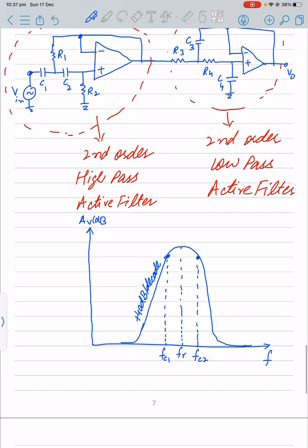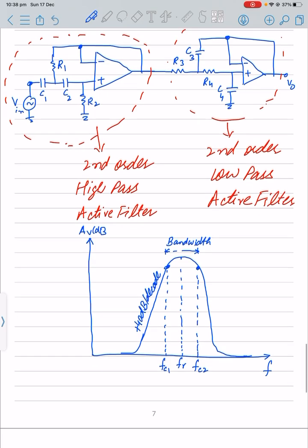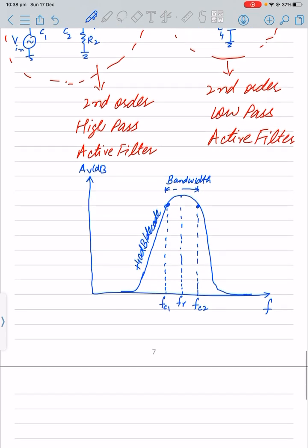So that will be the frequency response of this band pass filter. It allows only a bandwidth of some particular frequencies to pass through it, and it blocks the rest of the frequencies. One of the ways we have achieved it is by cascading a high pass and a low pass filter. The order is actually not important. You can put a low pass filter at the first stage and then a high pass filter at the second stage, but in every case our response will be the same.